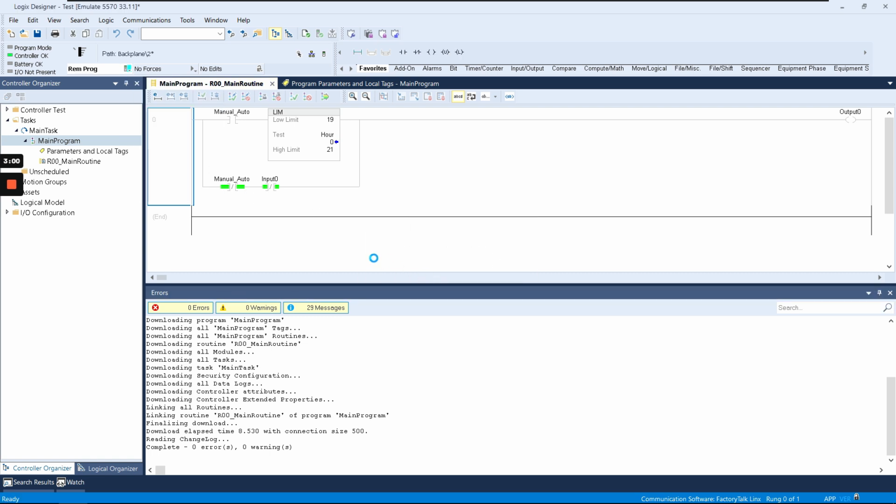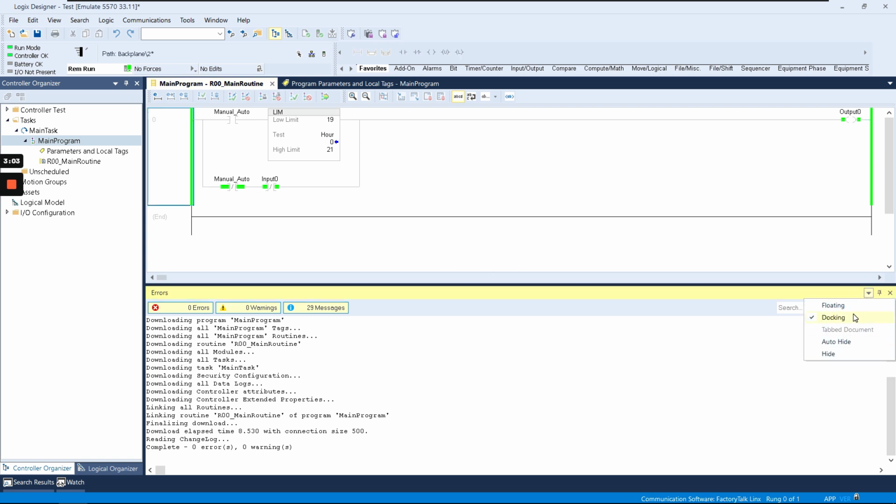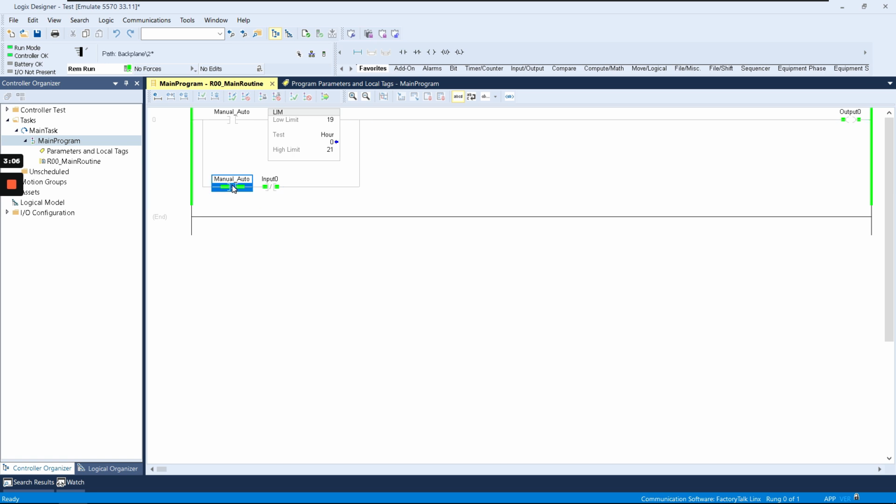But what I want you guys to see is, if we had an input indicating that it could be an automatic motion on the upper part, we have our first condition that our selector is automatic. Second condition, we should power on that output when it's between a certain time and certain time, which is between 7 and 9 p.m., or 19 and 2100 hours.